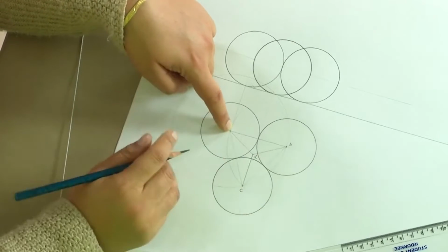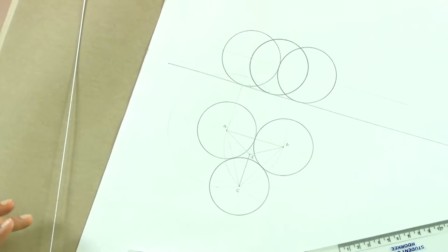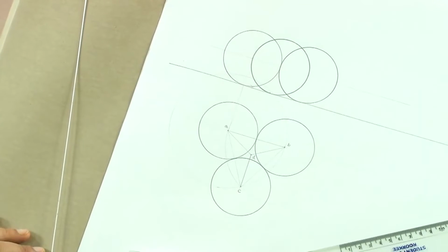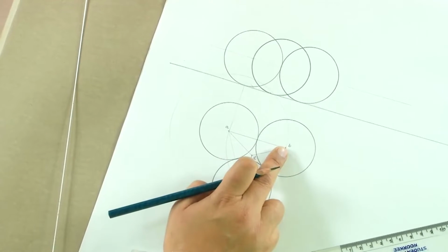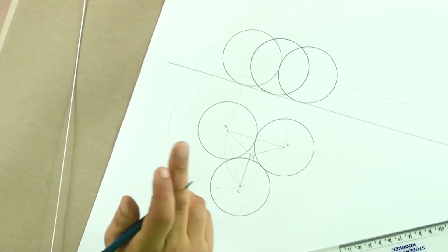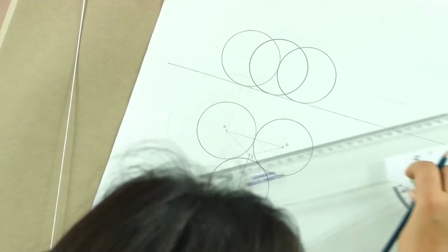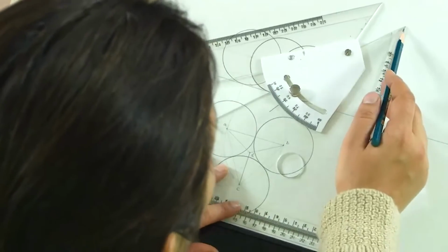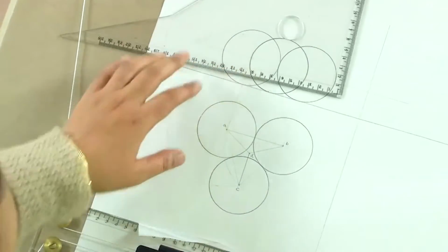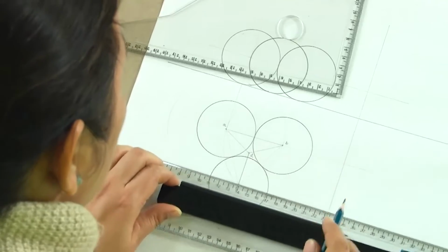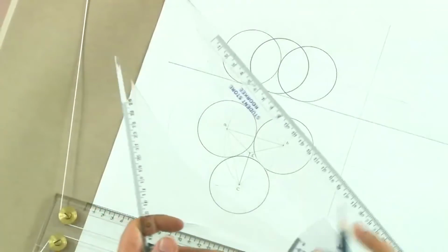So, this DA is also twice the radius, but unfortunately we will not be able to see this DA in its true shape, because it is making an angle with both HP as well as VP, and similarly this DB is also making an angle with HP and VP both. The only line is this DC, which is also making an angle with both HP and VP, but we have the side plane to which it is going to be perpendicular. So, all we have to do is take this line DC onto the side plane. Just like we did earlier, we will project it onto the side plane.